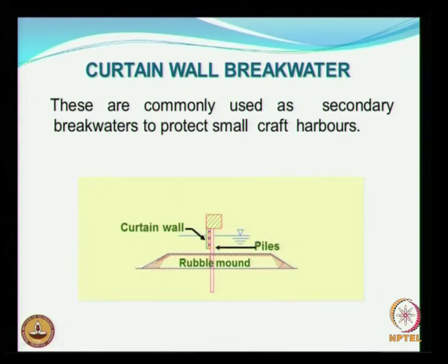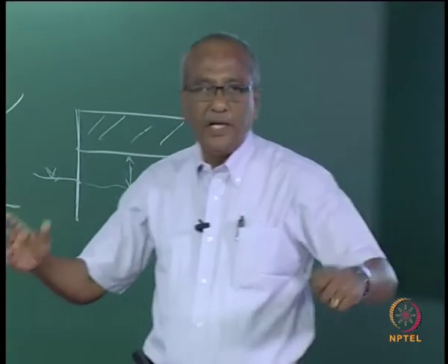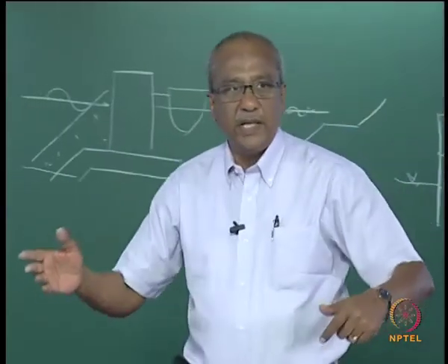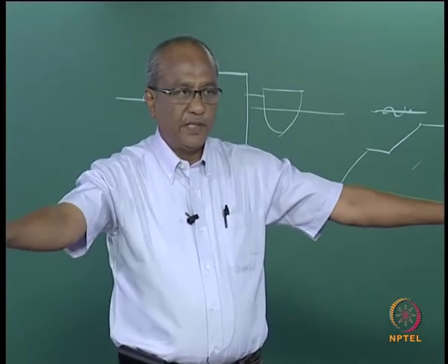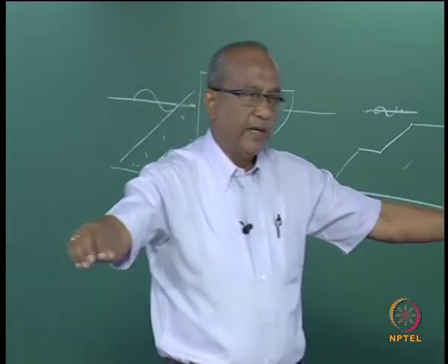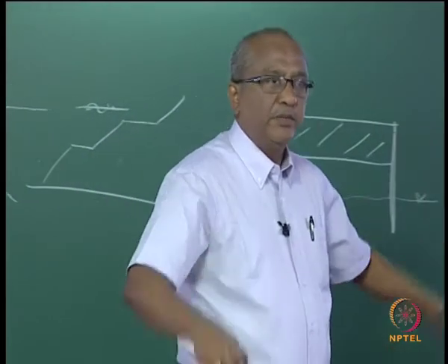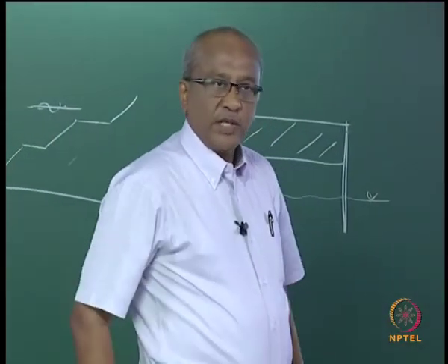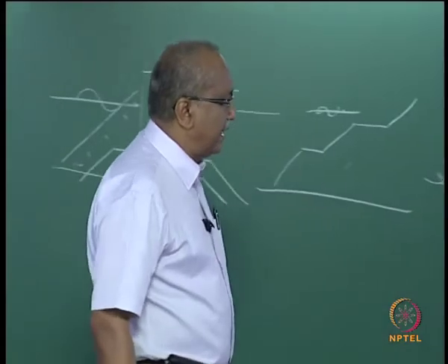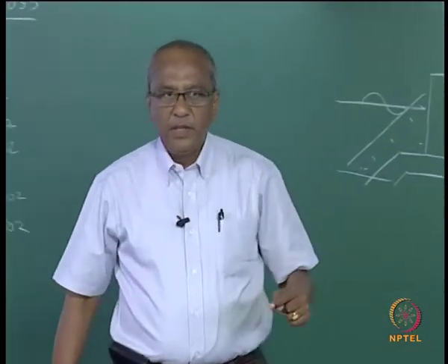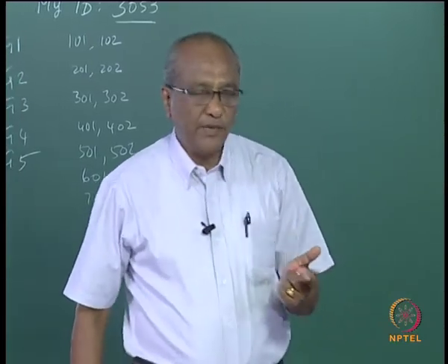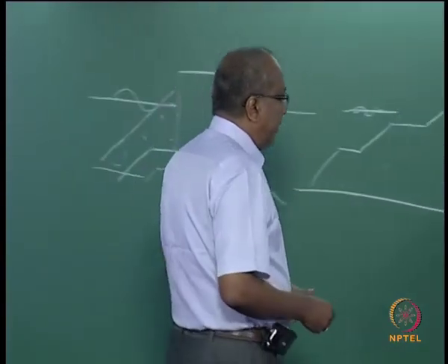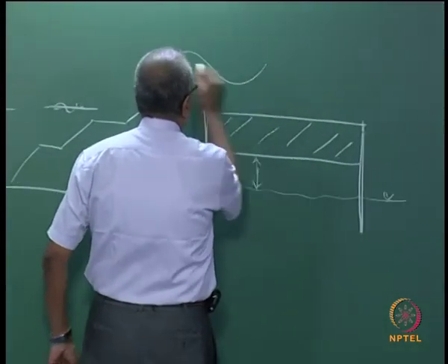In fact, you can also have this kind of a breakwater with moorings. So if temporarily you want to have some kind of a calm area within the shallow areas, you can just have this fixed through moorings, and then when you want to transport it, you can just remove the moorings and shift it. You understood? It is quite effective, but particularly in short period waves, in the case of locations where the wave period or the wavelength is less.